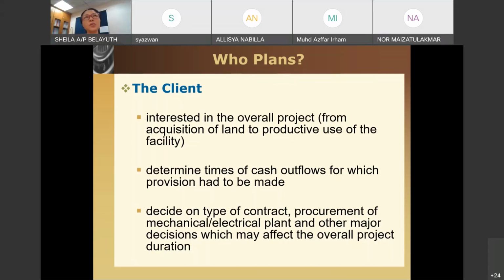Sometimes we think that M&E comes later, mechanical, electrical, all this comes later. But if the client requires everything embedded in your wall, in your slab, and so on, then it will need to come before you even concrete the slab, and before you build the brick wall, you need to hack in and install it, embed it in the wall, and so on.